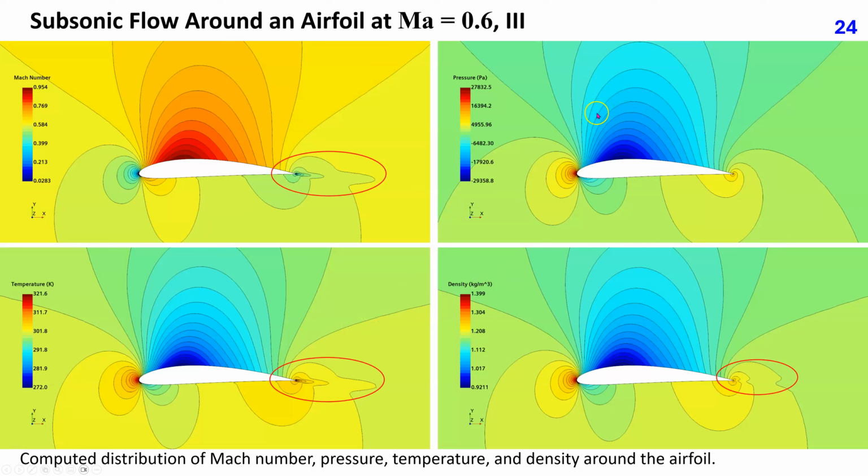The pressure contours are smooth everywhere, but in other variables we see disturbances downstream of the trailing edge. These are due to discretization errors and become smaller when the grid is refined. Here, second-order linear upwind scheme was used to approximate convection fluxes. Disturbances would have been much larger if the first-order upwind scheme was used.